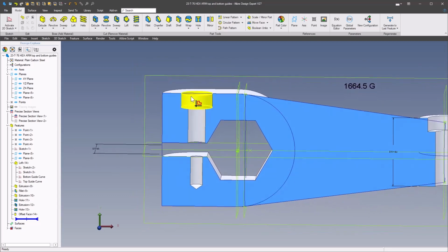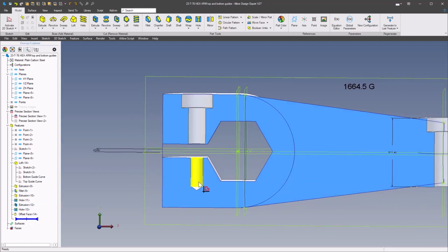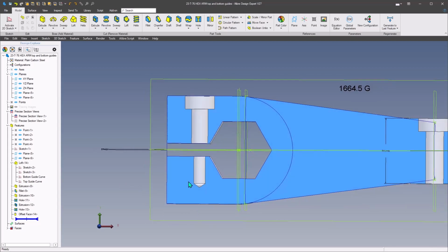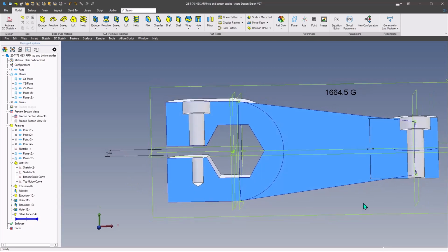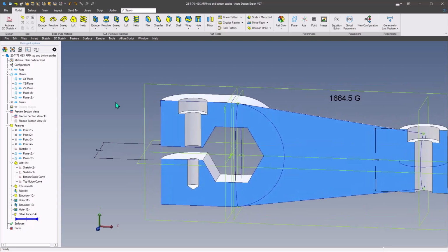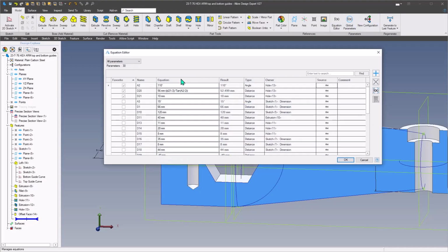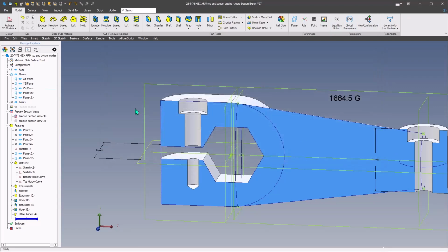But anyway, that gives me a hole tool that I can create 3 different size holes and a total depth measuring to the drill point rather than the bottom of the straight section of the drill. So if you ever need to create a part or drill a hole that's measuring the drill point rather than the drill depth, then hopefully you can use this equation to help calculate that and come up with a solution for your problem.